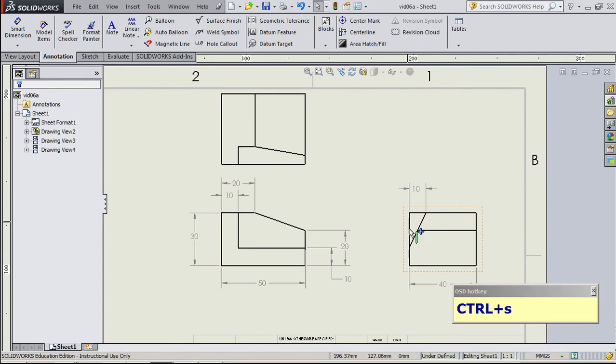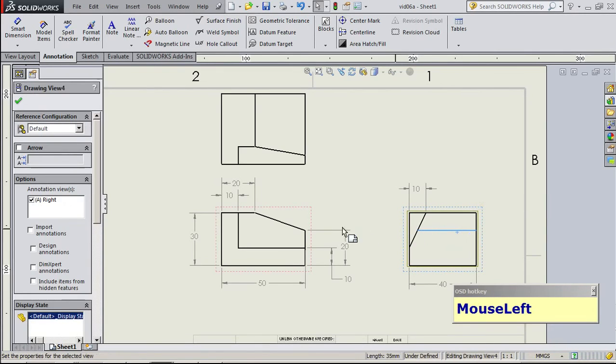Notice that I'm not giving any of the vertical dimensions. If I wanted to figure out where this ledge is, I would refer to the perpendicular view, the front view. Since this edge is aligned here, and this is at 20 to the bottom, I already know where this is located. I know the total width or the total depth here.